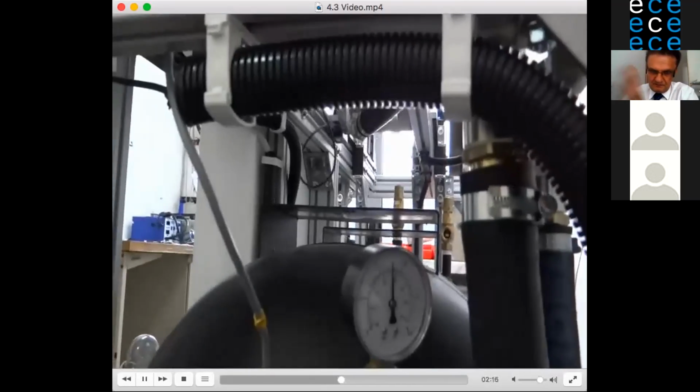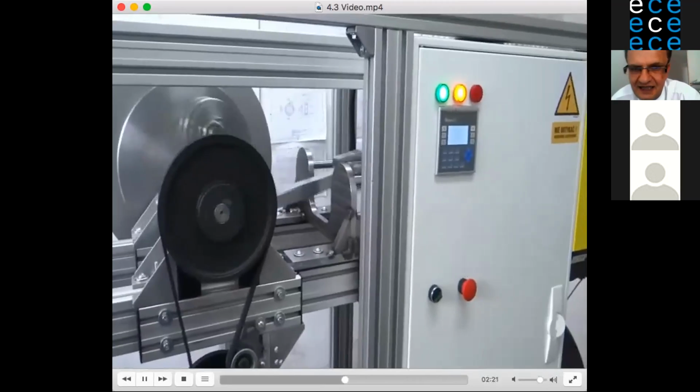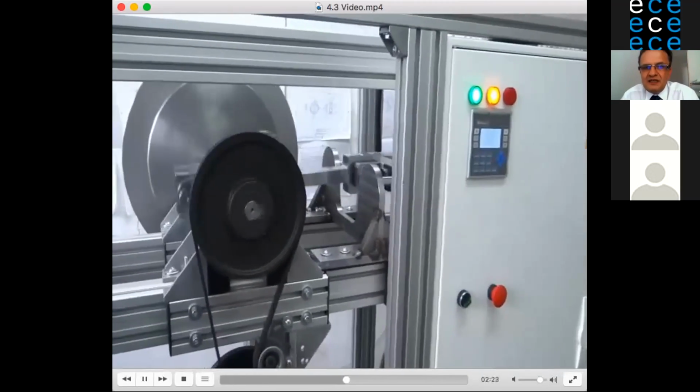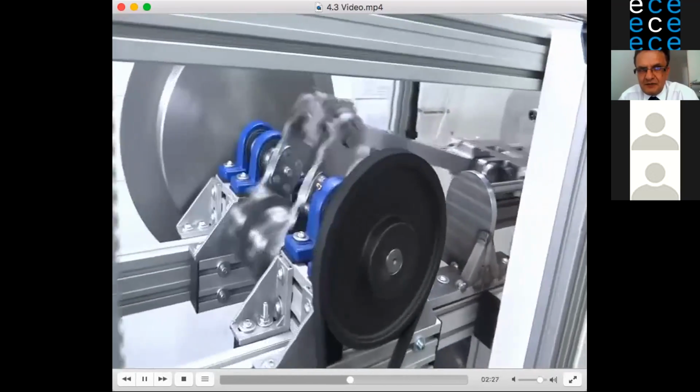This is the second stage. The machine is fed from the first stage, from the original or regular pneumatic installation, when we introduce some back pressure in some ports where mufflers were located.